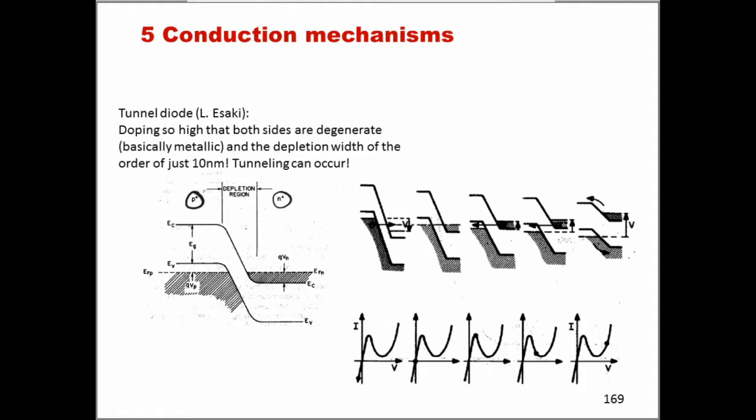The fact that they are heavily doped means that the semiconductors are effectively degenerate. This means that we cannot talk anymore of, for example, silicon with few impurities. Now there are really a lot of impurities. And so this effectively means, if you remember what we've said some time ago, that in a degenerate semiconductor the Fermi level is either very close to the conduction band or the valence band, or even beyond them.